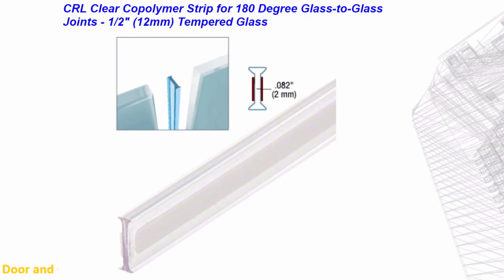And it's important that our glass deductions are for the thickness or the size of this material that goes inside of the joint. There should be no space in between here. This is a difficult type of joint to create because we have 1/8 of an inch of uncertainty in the glass size.